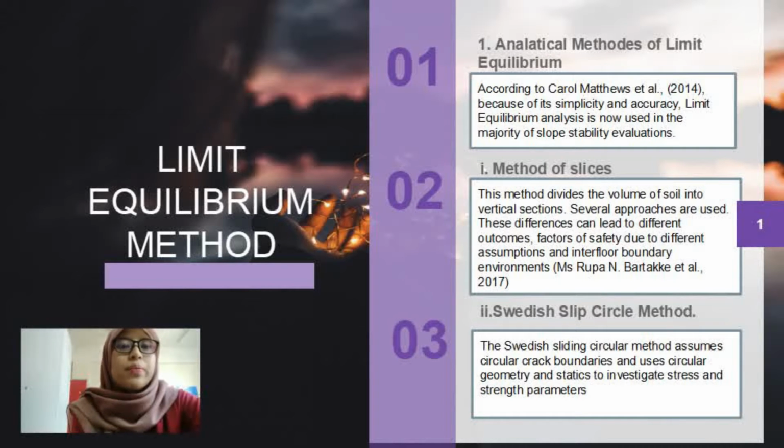For the Swedish slip circle method, it assumes a zero friction angle with respect to the ground or stone. That is, when the friction angle is set to zero, the effective stress term is zero, which equates shear strength with a specific soil adhesion parameter.